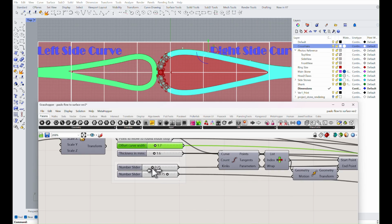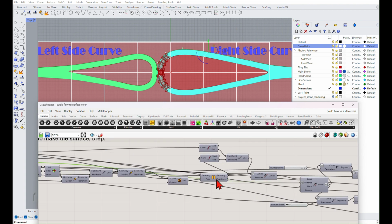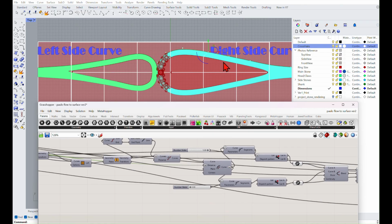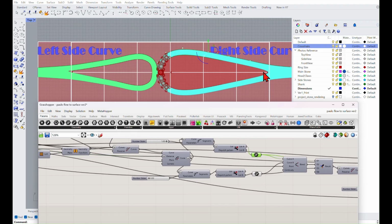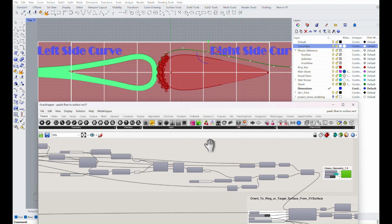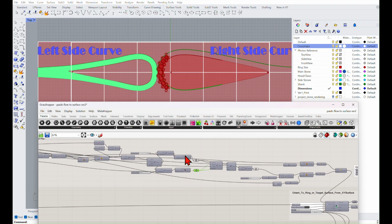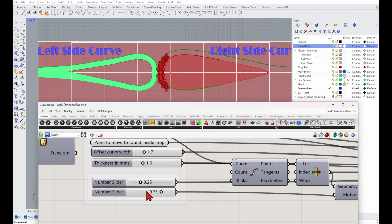Okay? These sliders here are to adjust the inside loop. So we've created the offset curve here, which offsets this curve here. We've shattered it. We found the curve we want, which is this top curve here. Let's turn this off. See this curve here? And then we're bending between this curve and this curve. These two curves are controlled by these sliders here.